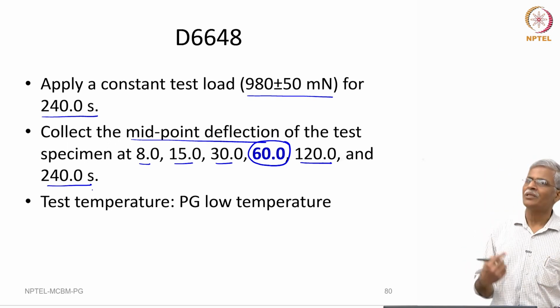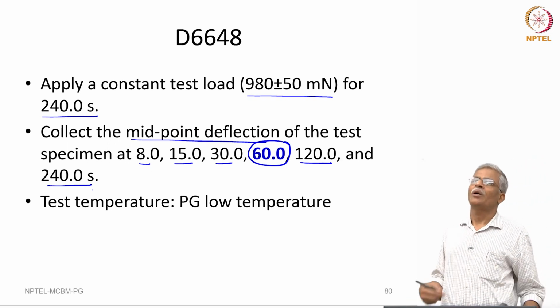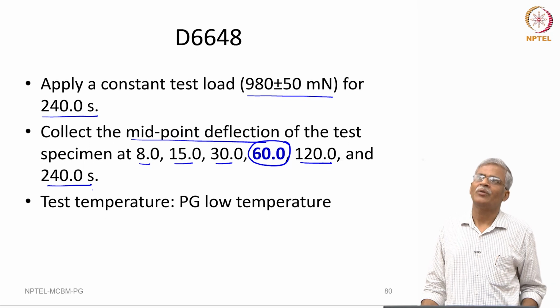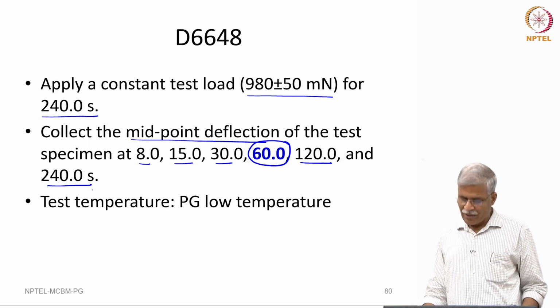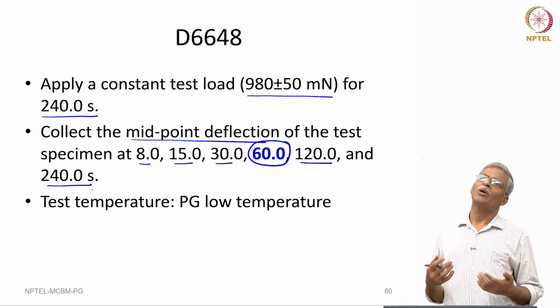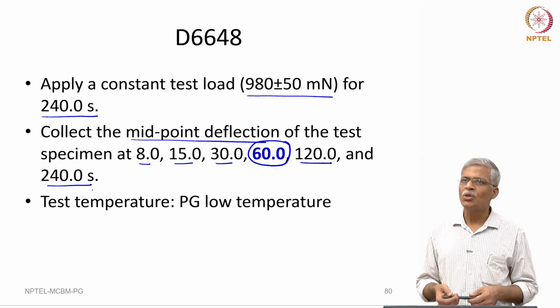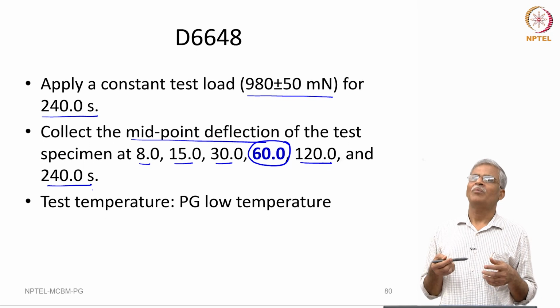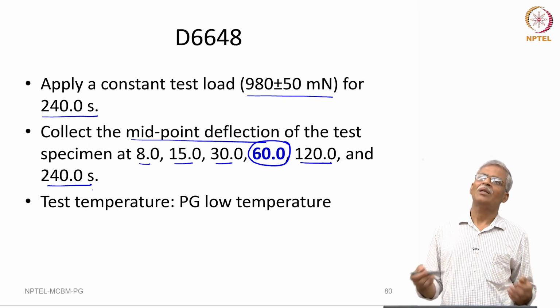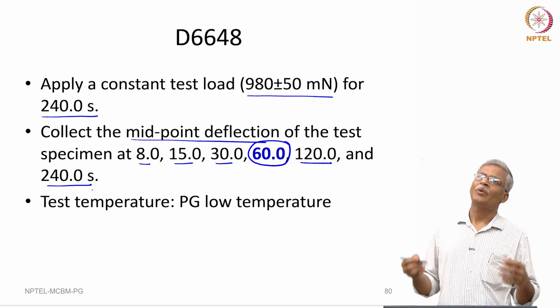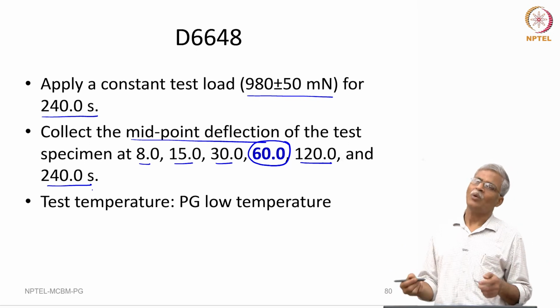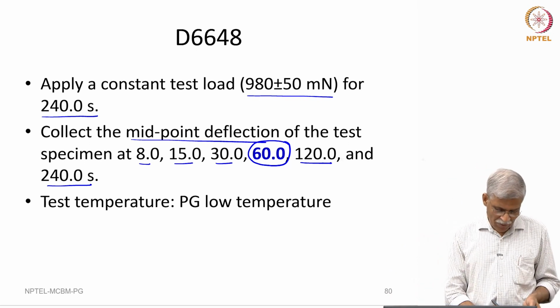Now, what is the temperature at which we should be doing this test? We will be doing this test at the PG low temperature. In fact, what we want to find out is whether the bitumen that we are going to use will be able to withstand the low temperature conditions prevailing in any geographical location, correct. So, we will be testing it at the PG low temperature.